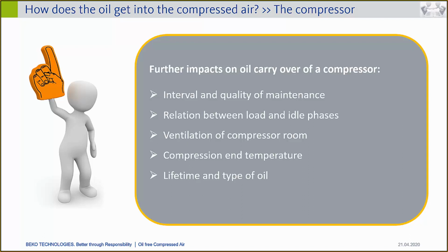Once the lifetime of a certain oil is exceeded, so when the maintenance interval is exceeded, the function of the additives will get dramatically worse. So they will lose their properties quite quickly. That means the foam generation will increase, and once the foam generation increases, the amount of vapor will also increase.